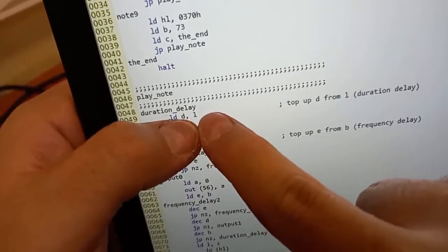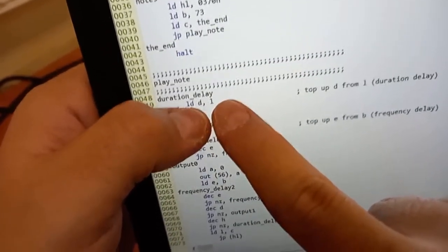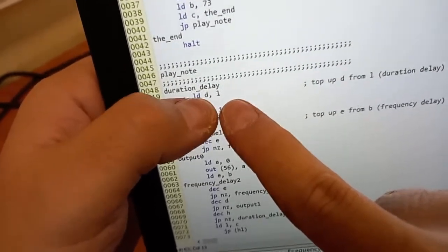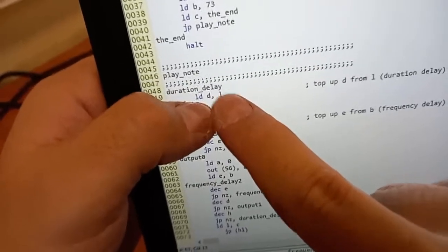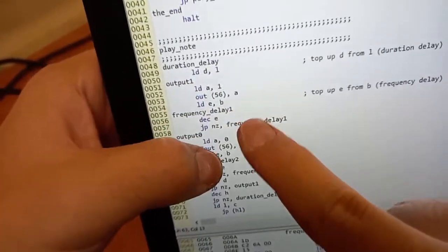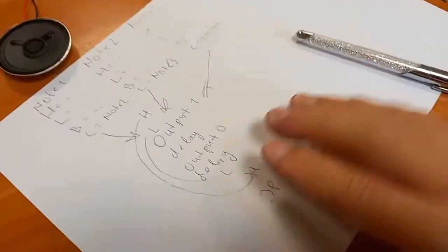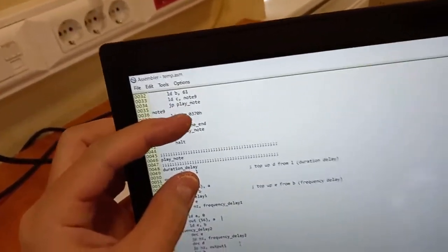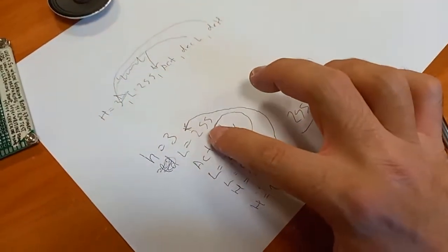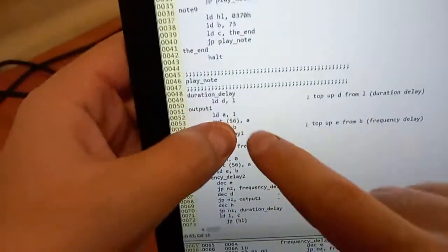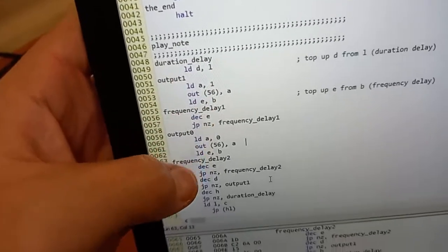That's why we don't decrement L. We copy this L into, for example, register D that we haven't used, and we start working with D, but L stays the same because we need to reuse it. We need to assign it once again, not 255, but with each node it has a different value. In our case, we cannot use 255 everywhere because the nodes are different, and we need to remember this number. That's why we're not touching this L. It's holding its number, but it's copied to D, and with D we're going to deal.